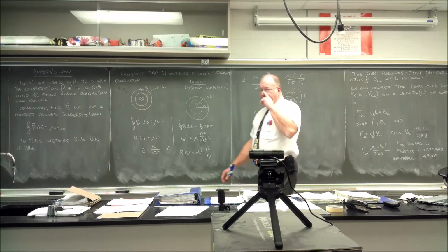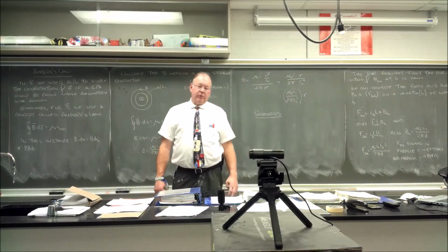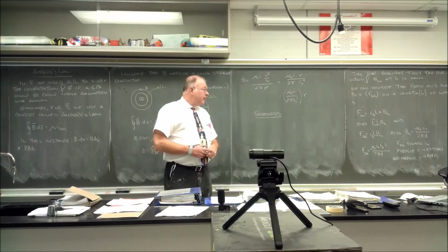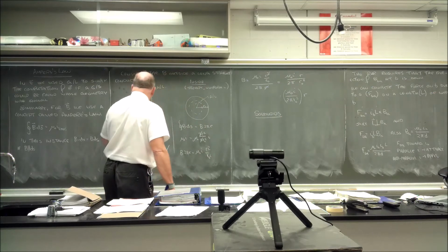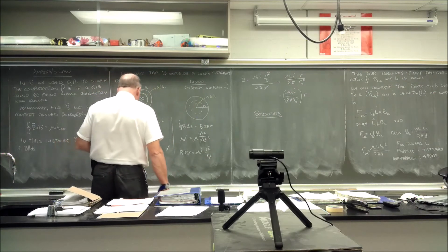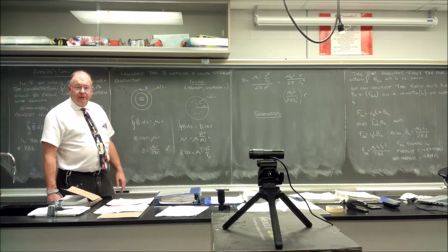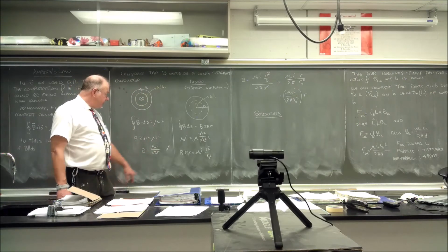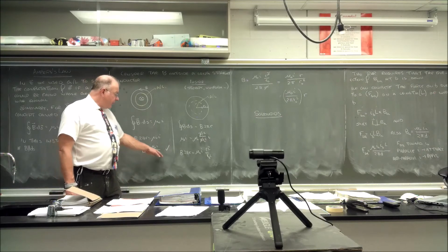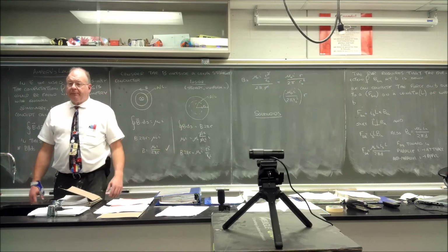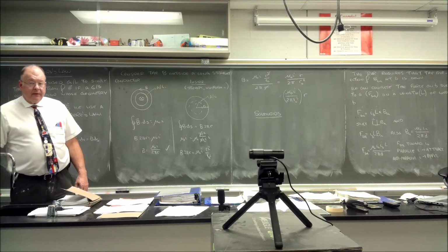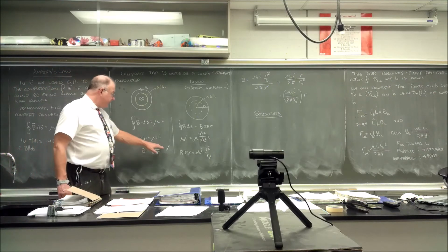Now, the magnetic field of a conductor is actually quite small, and we don't have to try very hard to see that. We take mu naught I over 2 pi r. Mu naught is 10 to the minus 7, whatever. So if this is 1 amp, and you're 0.1 meters away, say, then the numerator is like 10 times 10 to the minus 7.